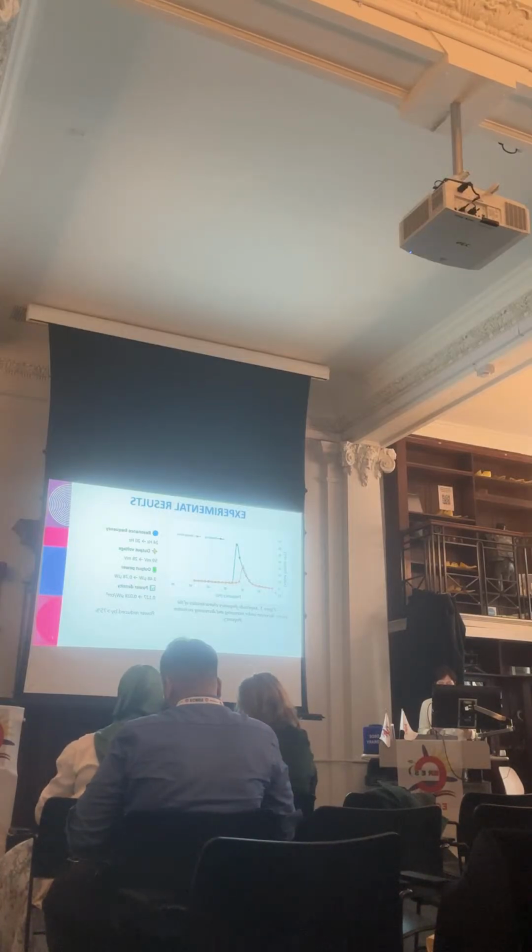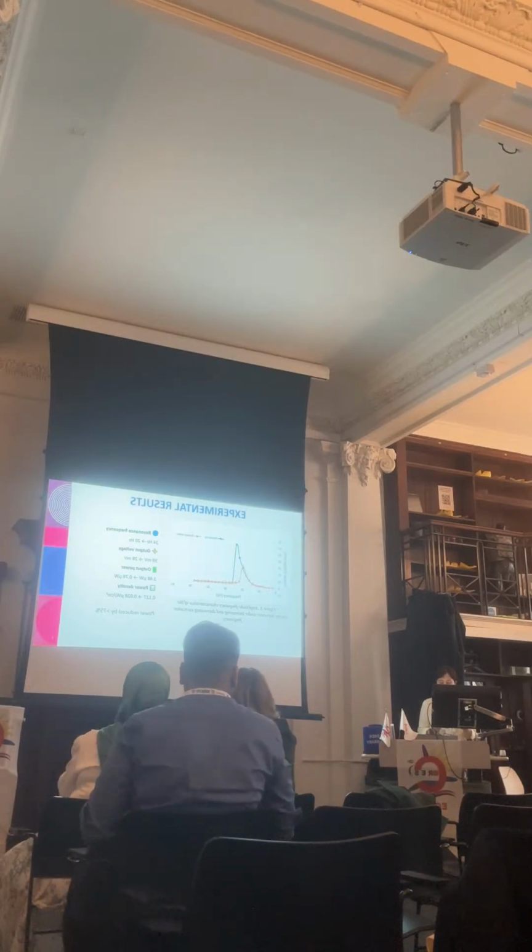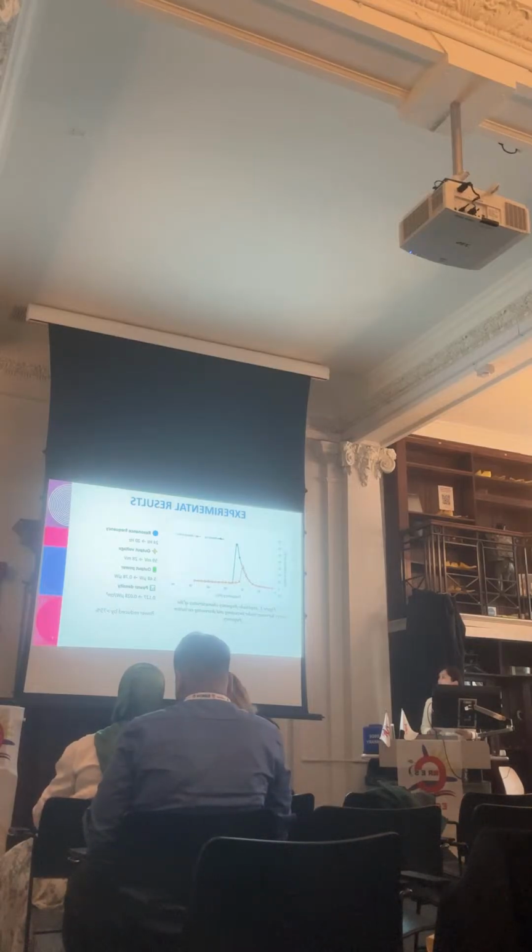During the sweep-down experiment, the resonance frequency shifted to 20 Hz, while the maximum voltage decreased to 28 millivolts. A similar reduction was observed in both the output power and the power density.